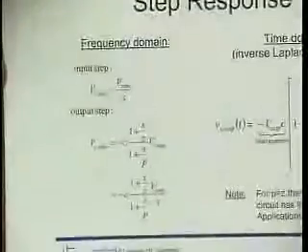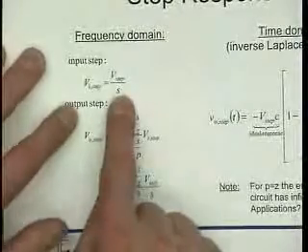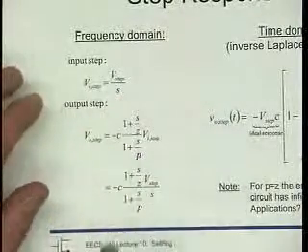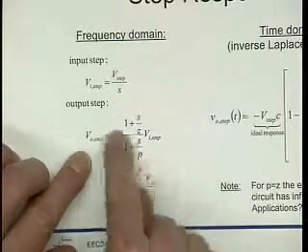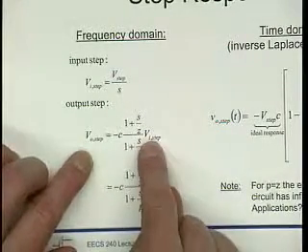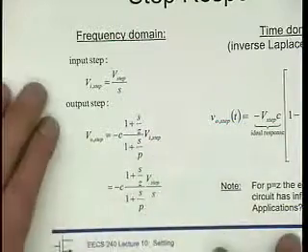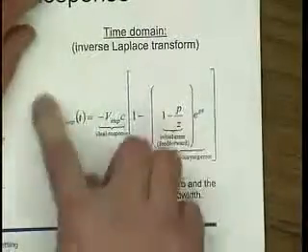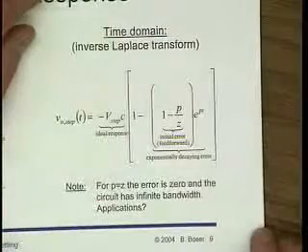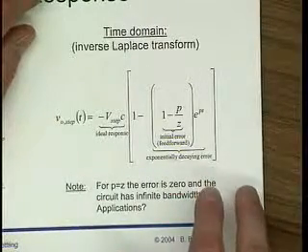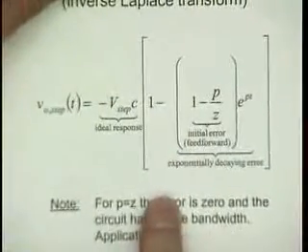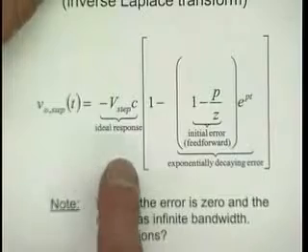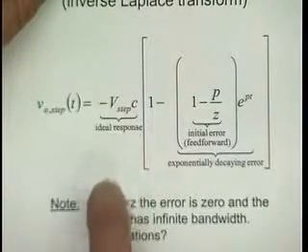Now the way we analyze this is, of course, inverse Laplace transform. So we have to put a step in. The Laplace transform of a step is 1 over s. So we have to take our frequency response, multiply with 1 over s, and then do the inverse Laplace transform. And if you can use more zoom, just about this here, a little more zoom. Hopefully you can read it in your notes. Is it focusing on your side?